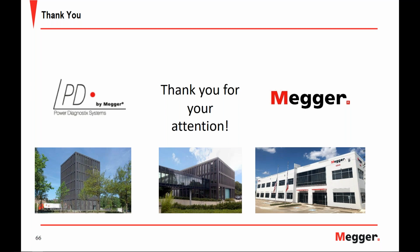So you see some phenomena that you can derive from an online and an offline measurement, but it's not always the case because some partial discharge effects are purely load bound or only detectable under real life conditions. But the offline measurement is then the right tool to serve as an in-depth verification to find signs of partial discharge phenomena that are ongoing during normal operational conditions. So that's more or less the answer to this question.